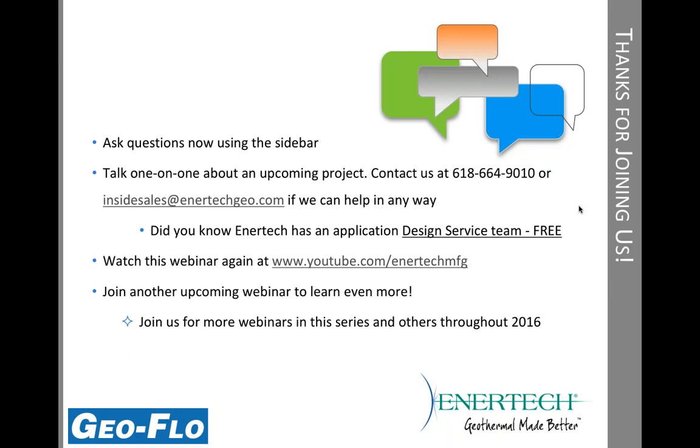And the controller actually has an input. So on the HydroConnect control panel, you have a closed contact that tells that pump to start running. And so as soon as one of the zones calls, it actually closes that contact. It tells the controller, hey, I need flow, and the controller starts looking at delta T. Now the controller automatically starts that pump at a higher flow rate just to give it time for the thermistors to react, and then after 2 minutes it starts adjusting based upon delta T.